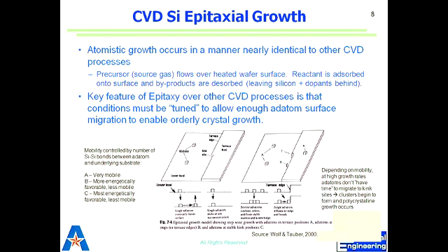But there can be defects, there can be nucleation also. But then it's the question of how you control your process to reduce the nucleation. You don't want them to stick somewhere else and cause formation away from the terrace, right? But this can happen. They can come together and form another island away from where they're supposed to be. So the conditions have to be tuned to allow enough adatoms to get to the terrace and be part of the terrace only.